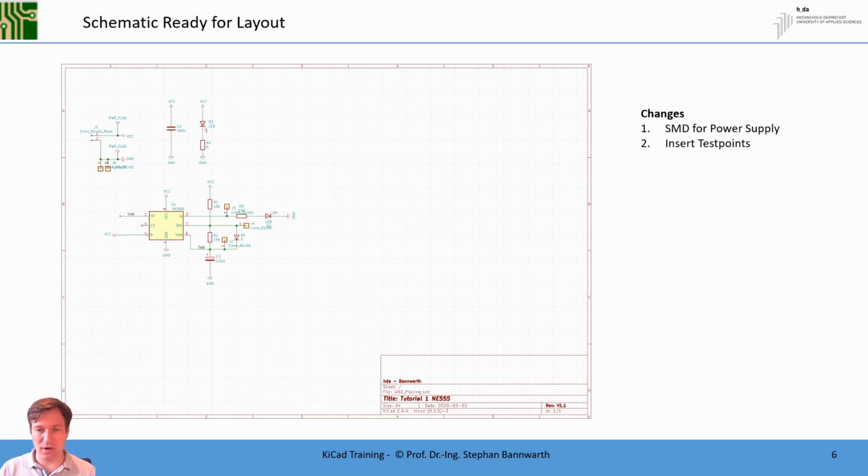And of course, when you go from your schematic, ERC-free schematic entering, to making updates, this new schematic of course has to be electrical rule check error free, and after this you increase your version number, please. I normally increase the version number from 1.0 to 1.1 when I go to the layout of the circuit.